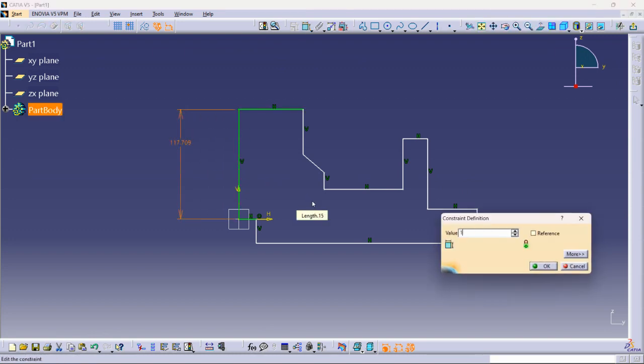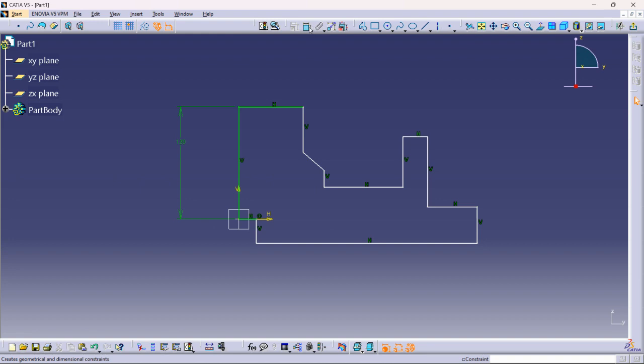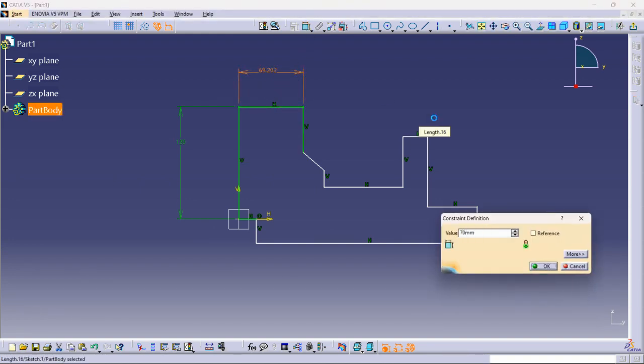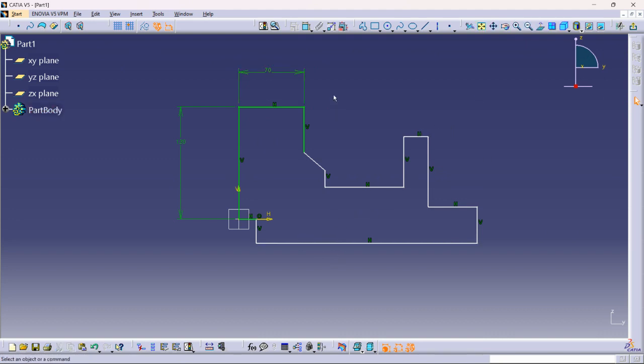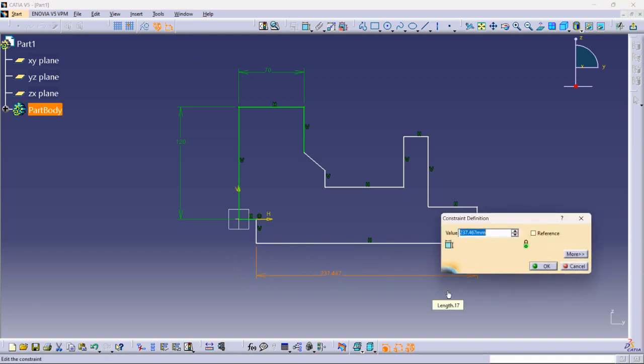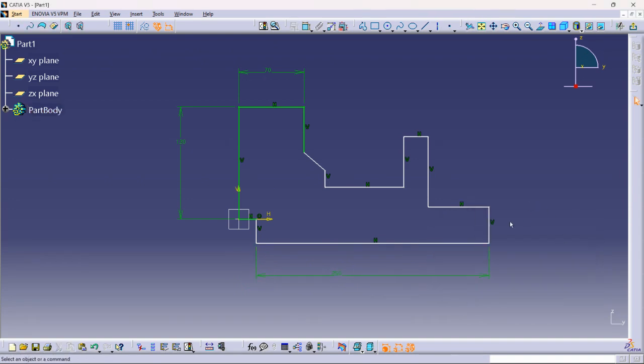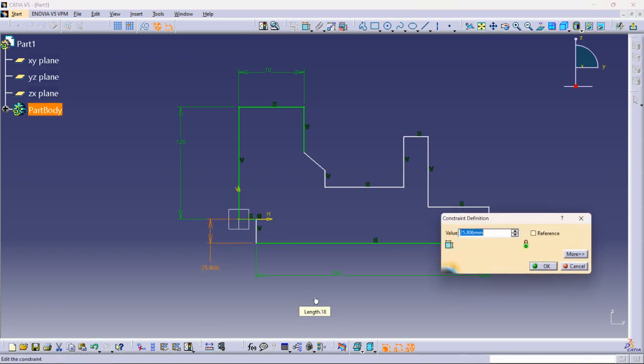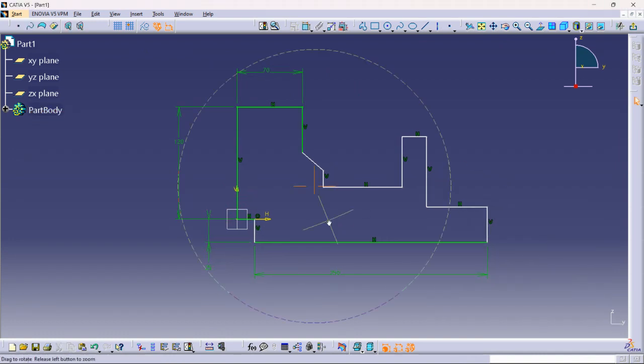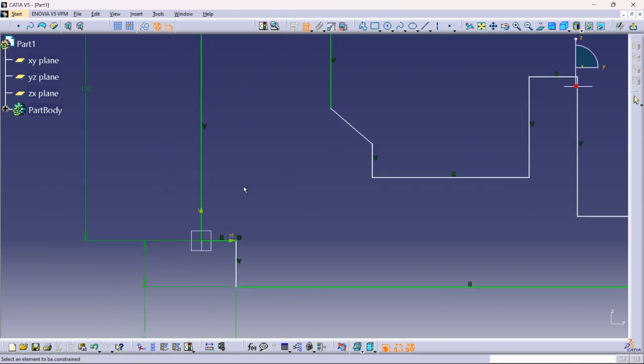Okay, and all sub options are the same. And here, I'm selecting up to plane, selecting this object, and here as the plane limit, I'm selecting this plane. You see, it is cutting up to the plane which is there. So this plane has to be a little more backward, then only we can see the effect.